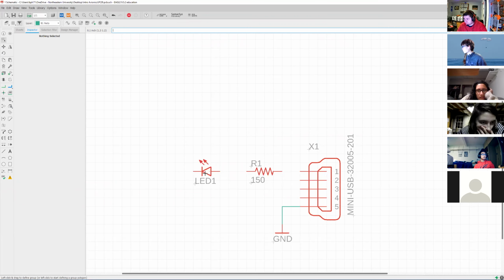Now the LED, so the cathode of a polarized part is indicated by a line. So the same thing with a diode, just a regular diode. And the anode is the positive side. That's not indicated by a line. You can also tell by the arrow that conventional current is going to flow on this here. We're going from right to left.